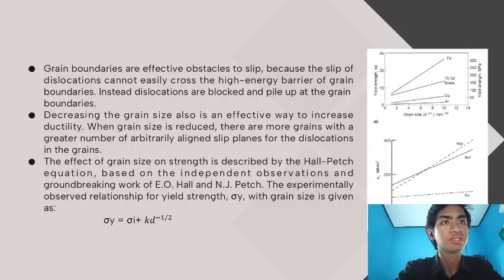Fracture resistance also generally improves with reduced grain size because the cracks formed during deformation, which are the precursors to those causing fracture, may initially be limited in size to the grain diameter.